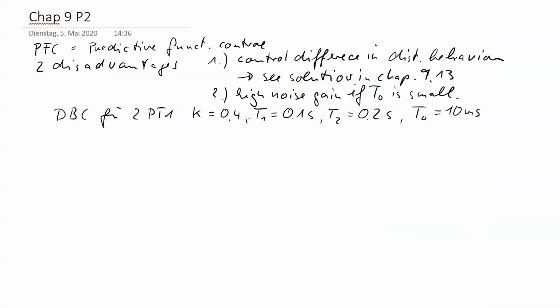So we note Q0 is 67. That means a 1 volt step causes a 67 volt step at the output. If I have 1 millivolt noise, just a signal which could change very fast, then this noise is a 67 millivolt noise at the output.